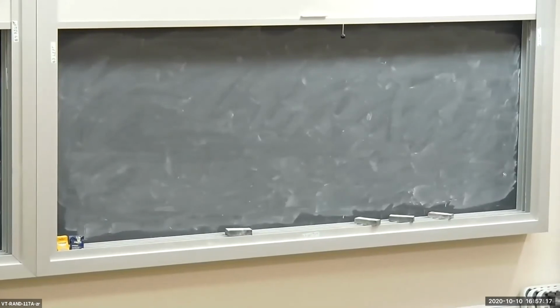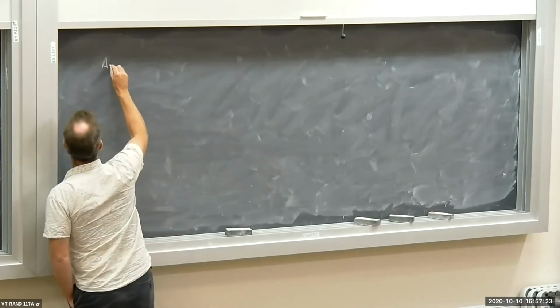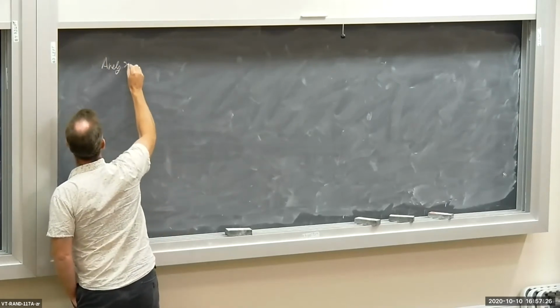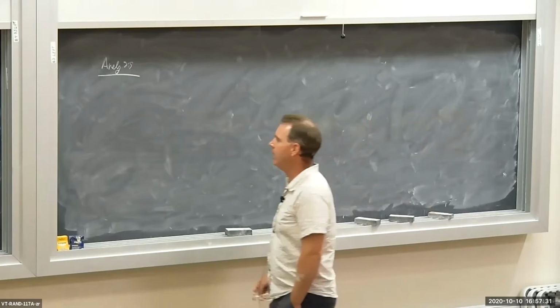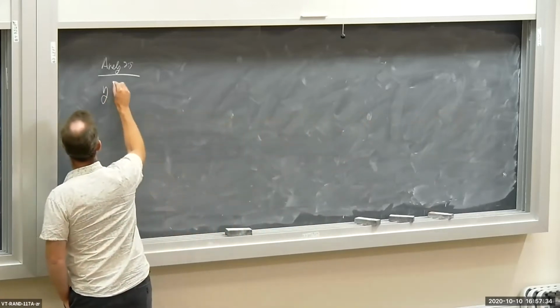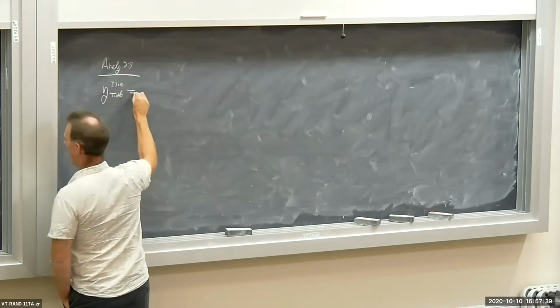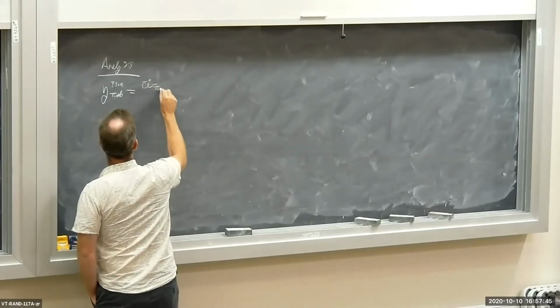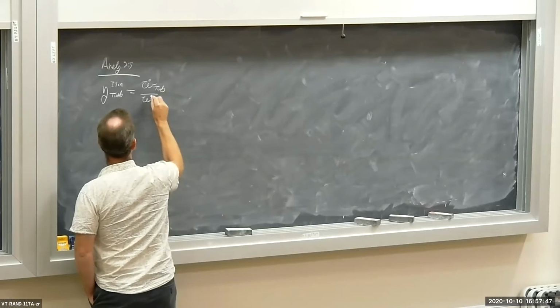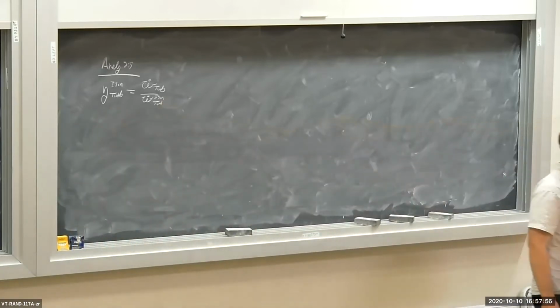Okay, so I want to find the work or specific work of the real turbine analysis. So I want to find the real work, the work for the actual device. If we write down the definition of isentropic efficiency for a turbine, not a compressor, a turbine, we get W dot turbine divided by W dot isen turbine, okay? Reversible or isentropic turbine.